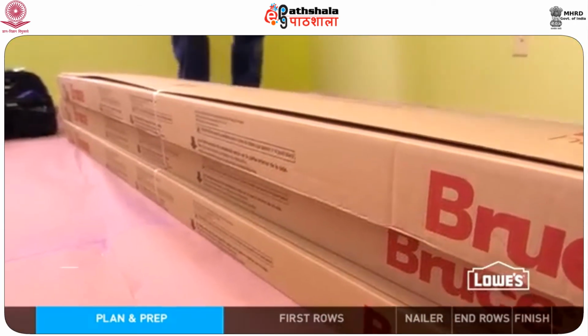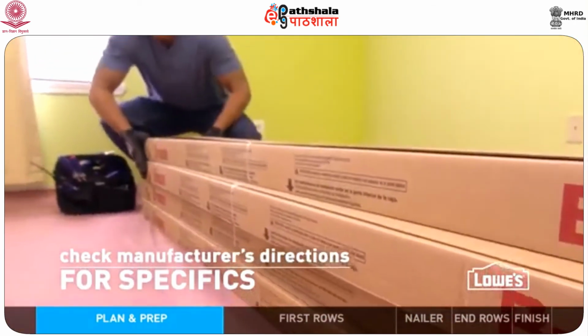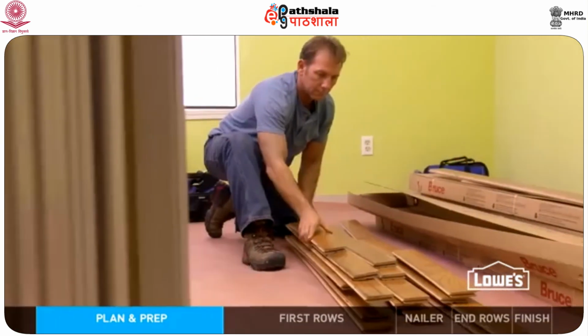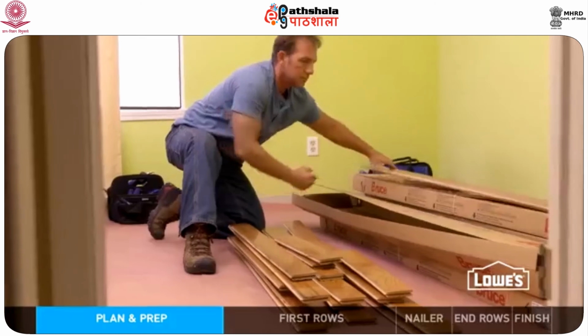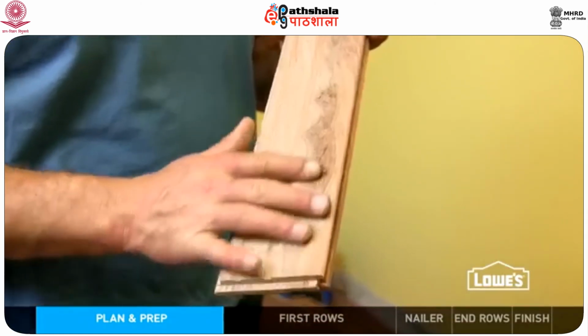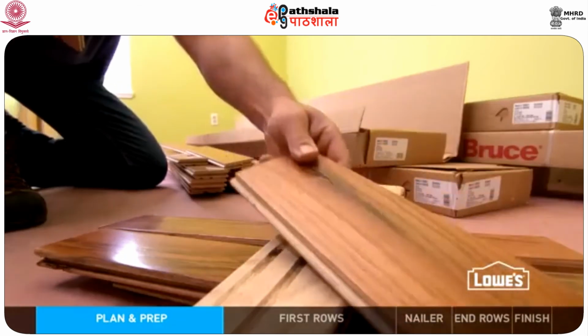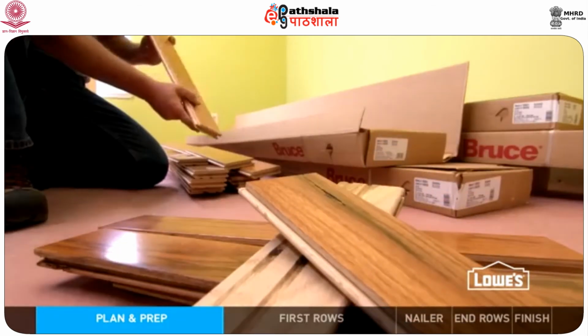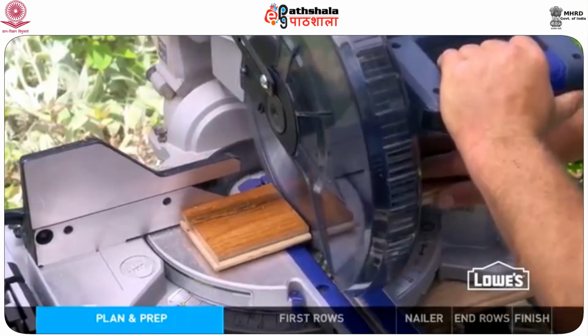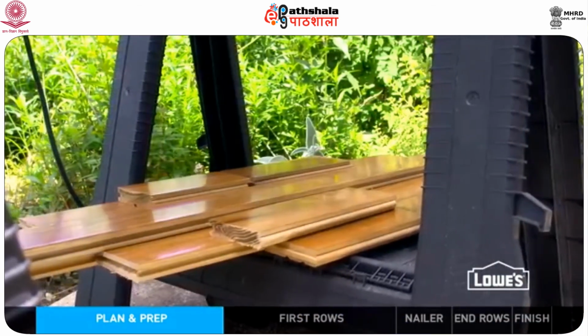When you have your flooring, let it acclimate to the room temperature and humidity for at least 72 hours. Typically, you remove the flooring from the boxes and stack it in the room. This is a good time to check for any warped or defective boards. Hold on to them. You can use the bad pieces to help pry the last row into place. Also, you might be able to cut off the damaged parts and use the good pieces for your install.